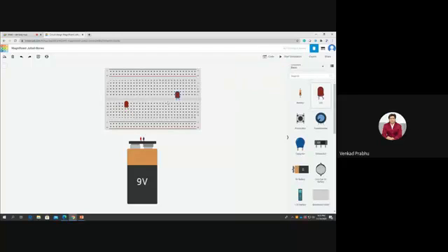And similarly another LED, like this. This LED's cathode leg is in the 11th row, so all the pin slats in the 11th row are going to act as a cathode, and the anode is in the 12th row, so all the pins in the 12th row are going to act as an anode, which is positive. And one more like this.